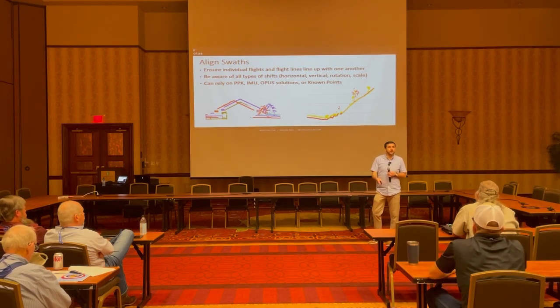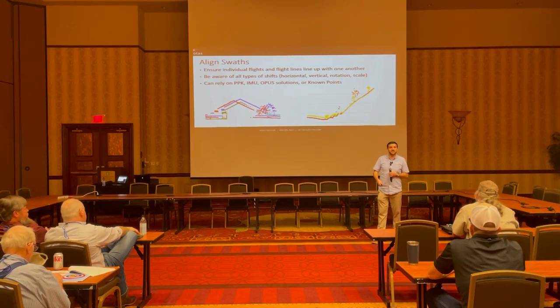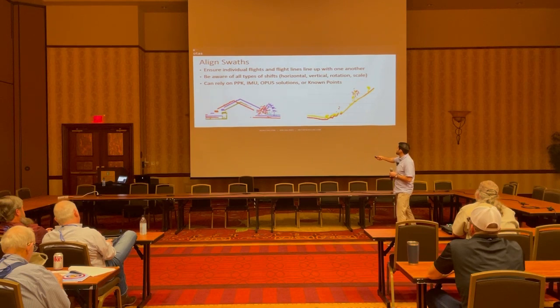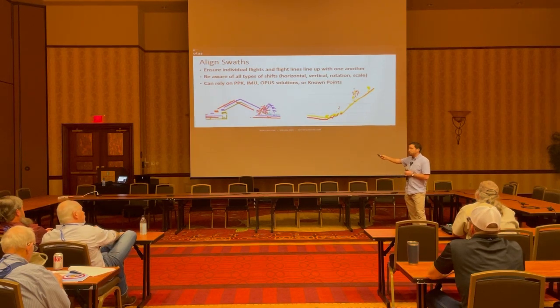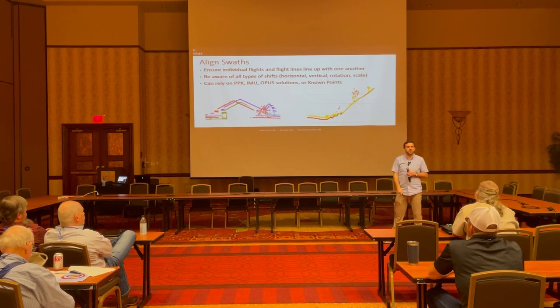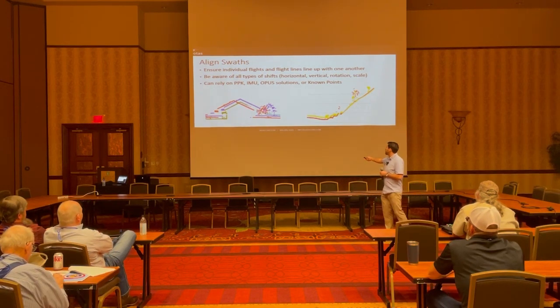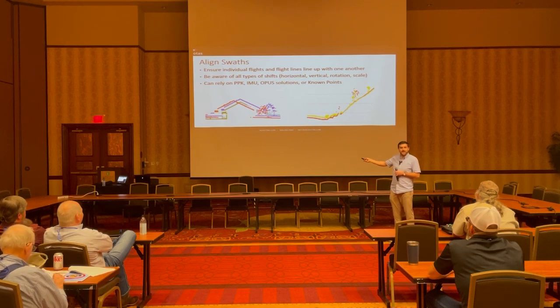And the reason I say run QA is because if you just assume your LiDAR data is good and throw this into a processing algorithm, it'll look at this and say, oh, well, the lowest one is going to be the ground. So it takes this green line as ground, and it calls this red and blue line vegetation, like shrubs or trees or something. When any human can look at that and say, no, no, no, that's a roof, and that is the same roof on all three, it's just mismatched.